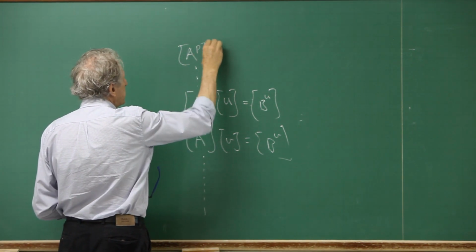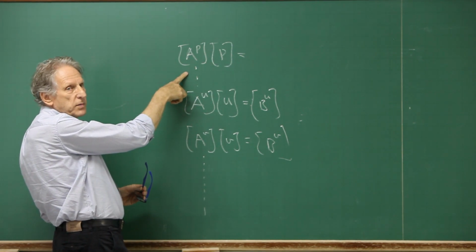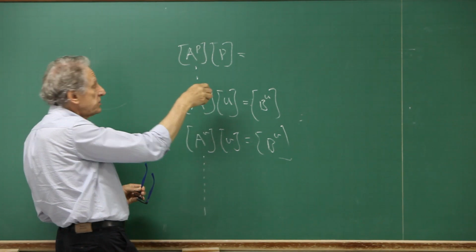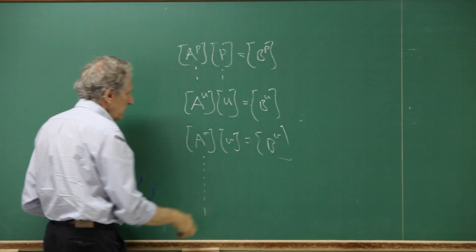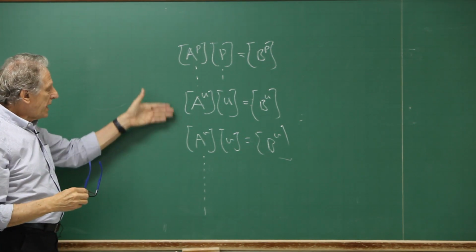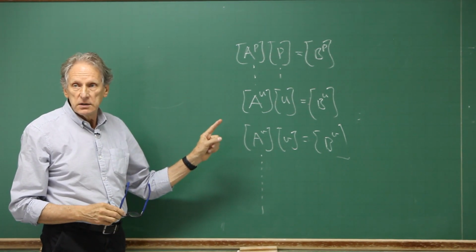I have a matrix for P. This is the transformation of the mass conservation equation into an equation for pressure. You solve one by one, but they are all coupled, right?